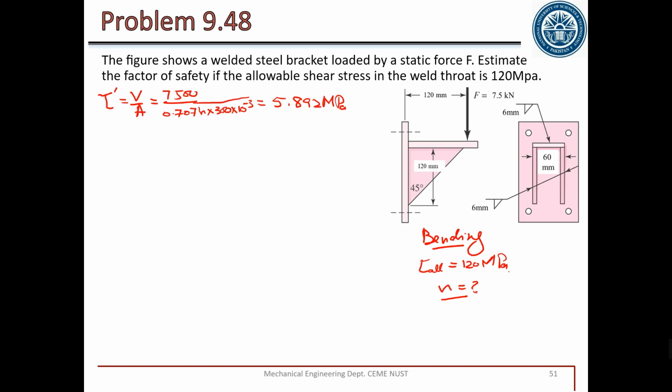This is also the easy part. Now the actual part is to calculate the second part, the bending stresses or tertiary shear in this case. First of all, we need to check if this figure corresponds to any existing figure in table 9-2. Going to table 9-2, out of these figures, figure 5 matches this description.